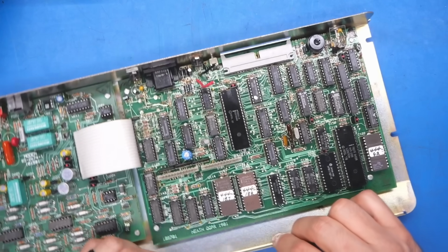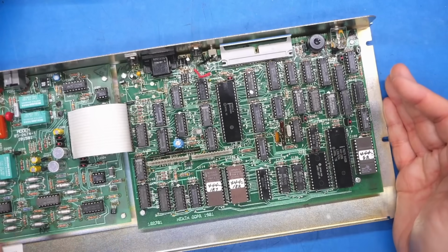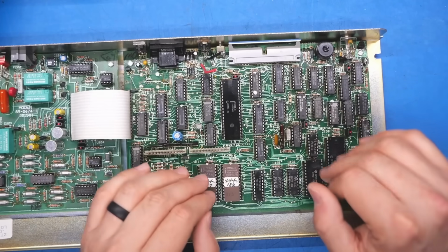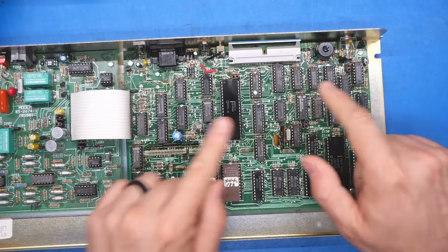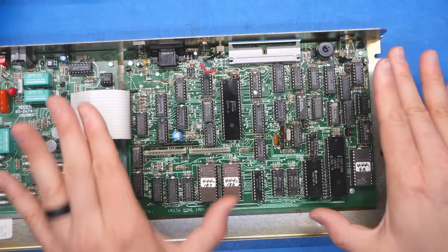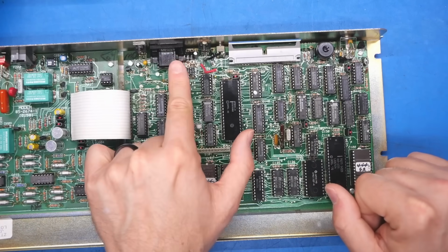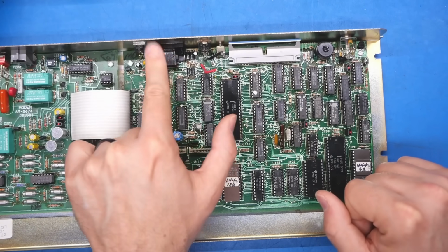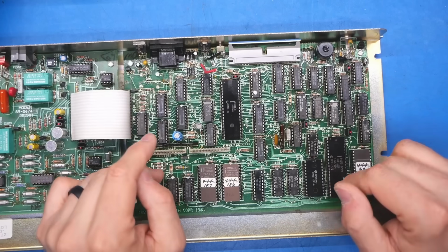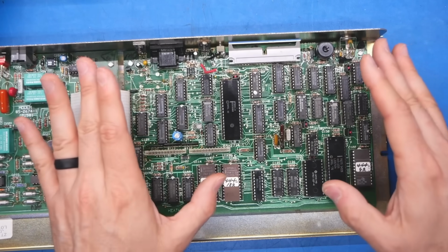Now, when it comes to the clock that this thing has, I don't think it actually has a crystal oscillator, like a 32 kilohertz oscillator. I don't see that anywhere on here, or any kind of clock chip. Everything is just normal TTL logic on here. My assumption is it uses the line frequency of the AC input to count cycles to maintain the time when the system is off. But the system is never actually off.